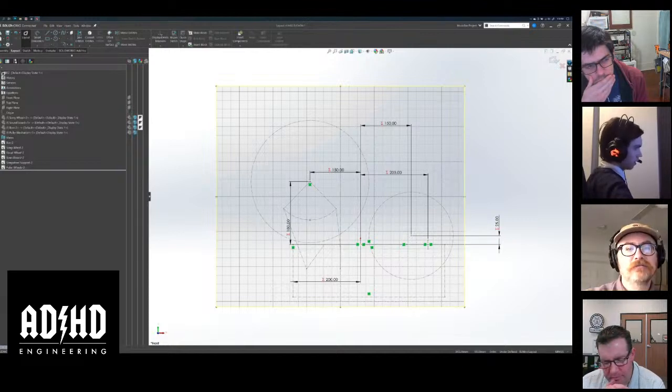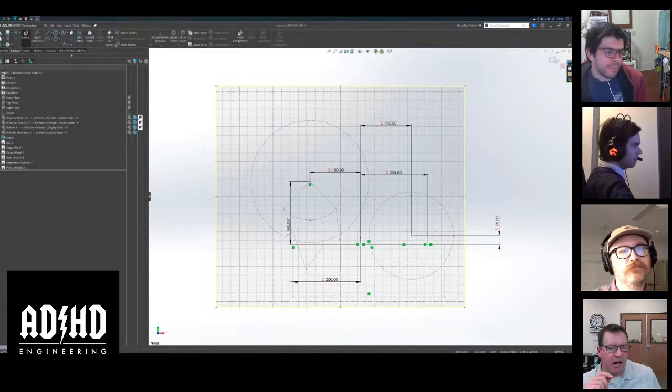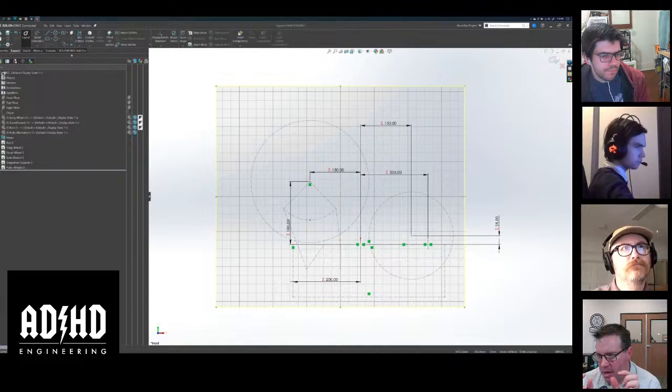The idea that I had, and the reason why I said the bolt holes, is that when I designed the paper pulling mechanism the first time, I had to change where the bolt holes were because of the width of the vibration mounts, and I wanted to make sure that there was clearance between the outline of the motor and where the sandwich mounts are.